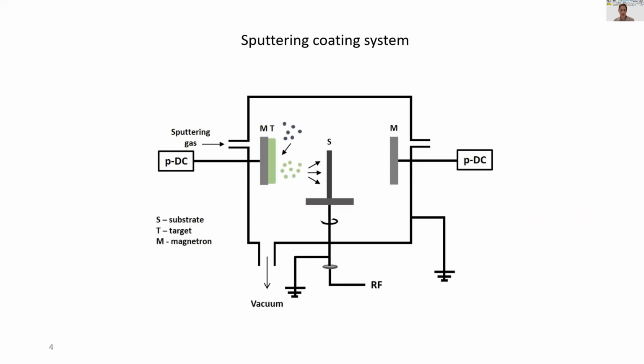The deposition of the coating was carried out in a vacuum chamber by a magnetron sputtering technique driven by plasma formation. The chamber contains a set of two magnetrons, and a bias power supply connected directly to the substrate to obtain improved coating properties.